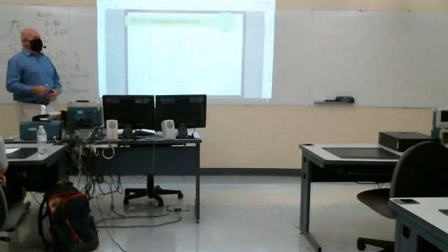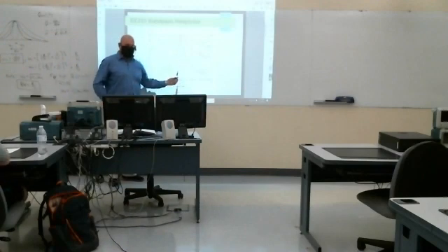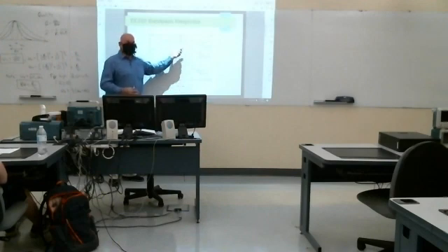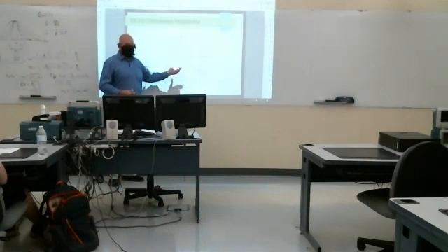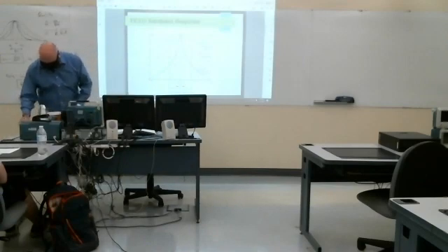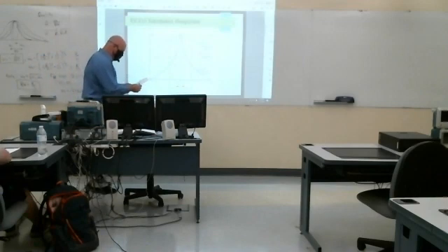Now, you don't always want a high Q circuit. If you're trying to pass maybe just a single tone, a single frequency, you might want a high Q circuit. But depending on the Fourier transform of the signal that you're dealing with and the signal content, you typically want to try and pass all your signal while filtering out anything else. I'll leave that up there. There are some other pictures I want to show.